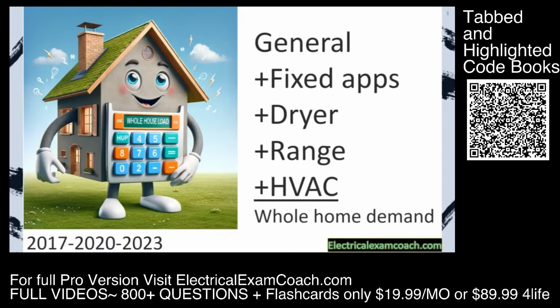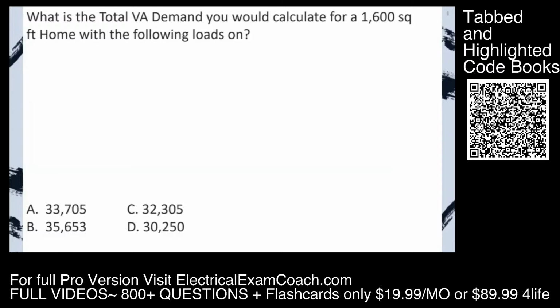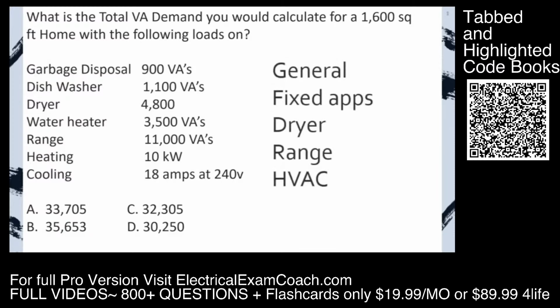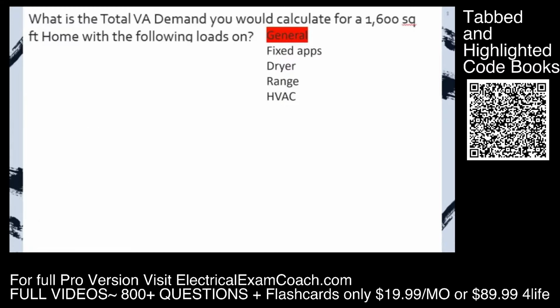Let's get to it. What is the total VA demand you would calculate for a 1,600 square foot home with the following loads? Now, I know this looks daunting, but we're just going to take it one piece at a time. You've worked very hard up until this point, and I know you can do it. I want us to get used to laying out all of our calculations like this. On our piece of paper, write general, fixed appliances, dryers, ranges, and HVAC, and we're going to fill them in one at a time. Step one is to find our general lighting and receptacle loads.